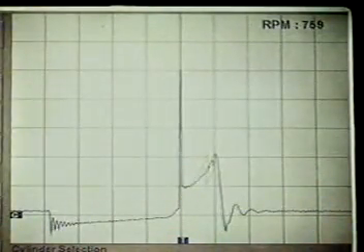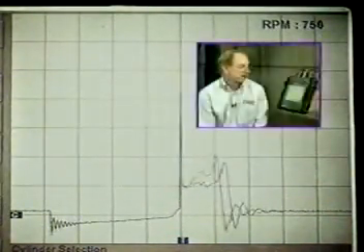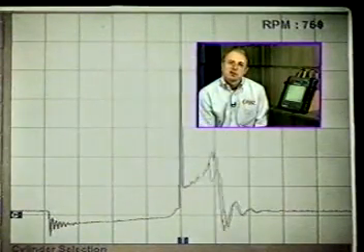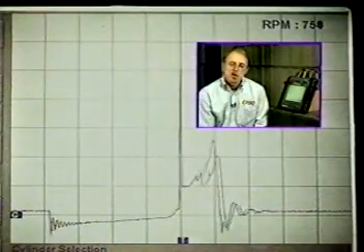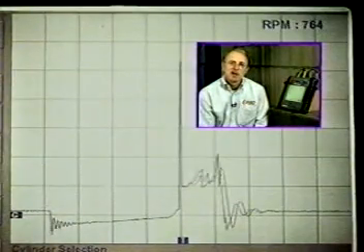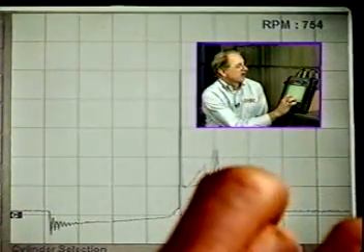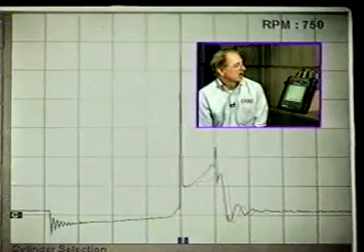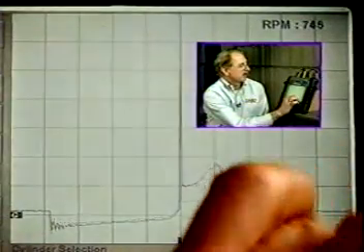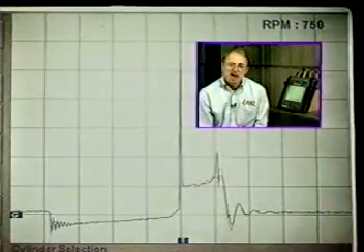You're now looking at cylinder number 5. It's pretty much showing you the same thing as number 2 cylinder. The spark line is bending upward. It's shorter than normal, verifying the fact that we have another lean cylinder. Let's go to cylinder number 3. Looking at cylinder number 3 spark duration, it's a little bit better. As you can see, it's hanging at about 1.2. Let's go on to cylinder number 6. Looking at number 6, it's a halfway decent cylinder too. So what you basically looked at on this 6-cylinder engine is 3 cylinders have a spark duration period well below the 1.3.